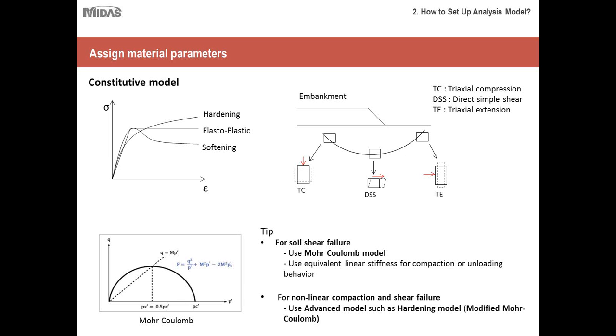But if you want to perform a non-linear compaction and shear failure analysis on the soil, let's say you are dealing with soil strata that are not very stable, that are poor soil with large volume changes that can happen, then that type of soil should be modeled using constitutive material model like advanced models such as hardening model or modified Mohr-Coulomb. So this is again a brief recap from what we have discussed or learned in the previous sessions as where to use what type of constitutive material model.